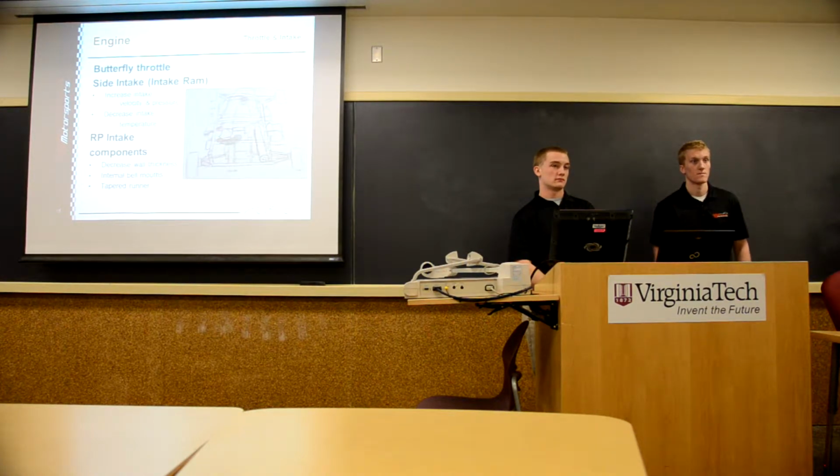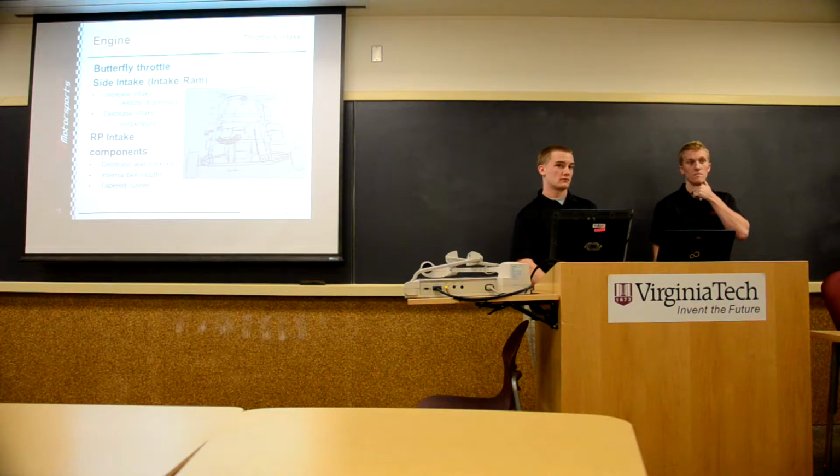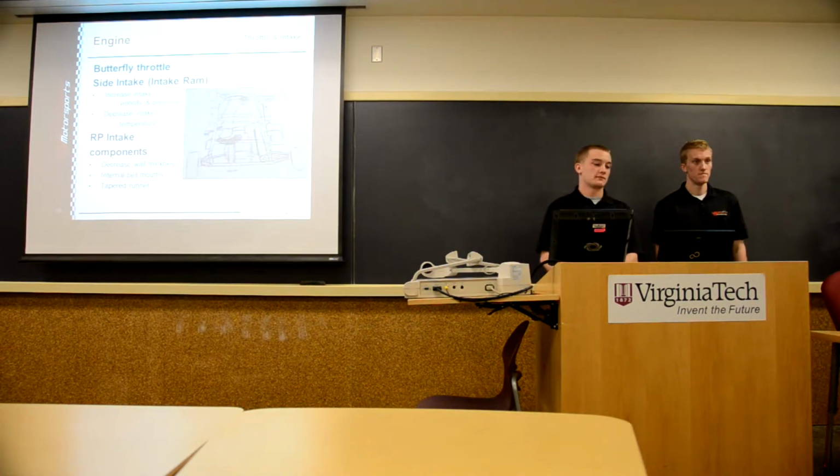And also just do a quick hand calc on whether the ram air intake effect is actually worth something, because at least in the Formula 500 community, that's heavily debated at 120 miles an hour if it's doing anything. So that's not necessarily to say that it's not going to work, but at least in some cases it doesn't always work. So make sure your situation will work for it.